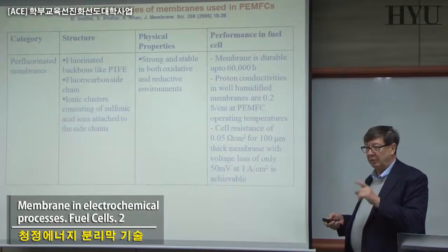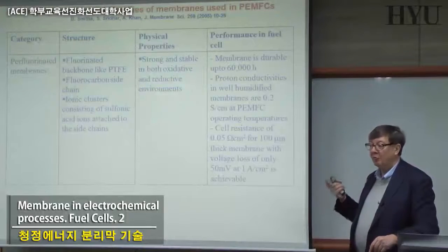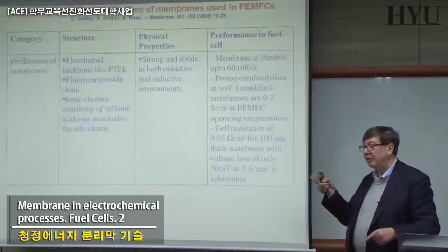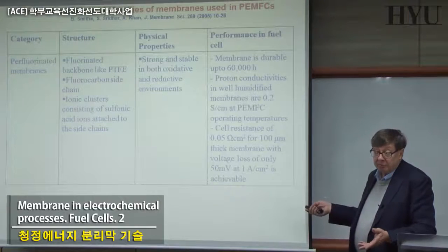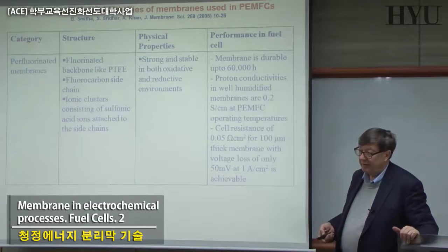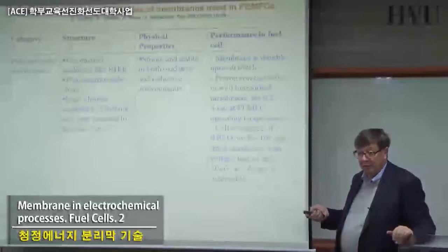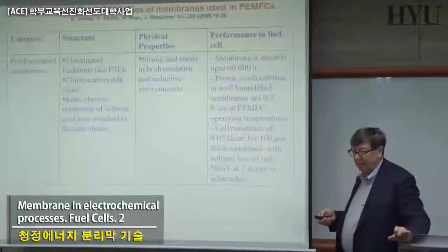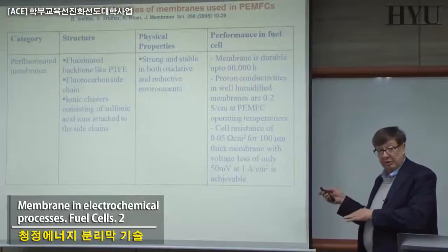If you are using PEEK, polyether ether ketone, you have to make sulfonation first. Sulfonation gives the protons that can go across, and if you can increase the charge density in such a way that you can compete with Nafion, you are lucky. It's not yet happening, and we will see what you can try to do to solve the problem, because this is a big problem.